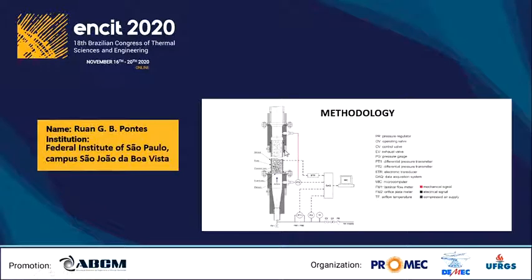The riser is made of dielectric material, and in this way it is possible to use a non-invasive electrical charge sensor to monitor the electrical charges generated by the flow. An electrical charge transducer is connected to the sensor, which allows an adjustment for different signal intensities. Furthermore, the pressure fluctuation across the bed is measured using a differential pressure transducer.